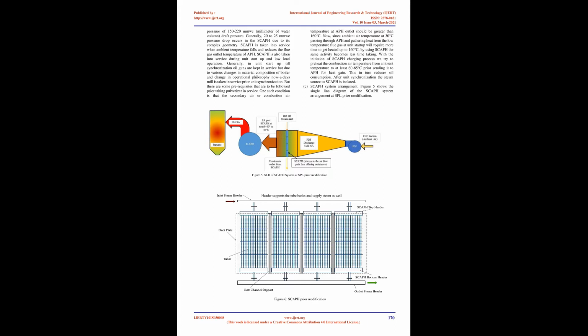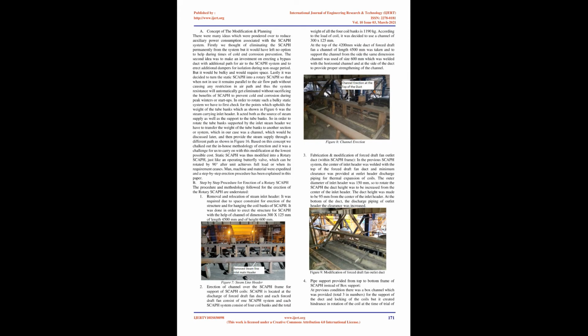Ltd. Table 1 shows the details of the forced draft fan operating parameters installed at SPL and manufactured by Shanghai Boiler Works Co. Ltd. Internal diameter of the fan 2818 mm. Diameter of the impeller hub 1412 mm. Stage number 1. Number of blades per stage 16. Blade material HF1. Screwed connection between the blade and blade shaft. Impeller adjustment range -30 degrees to +20 degrees.